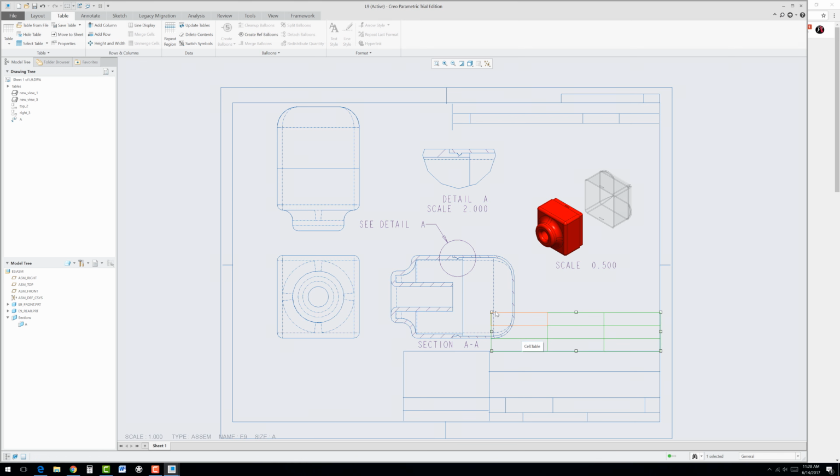To change the size of this, it's really kind of nice. You could click from here, go from left to right, and select that group of cells. And now if you right click, you could go to width and change the width here. Instead of 10 characters, this is only going to have a couple characters, so we could really just go with probably 3. Preview it, hit OK. This one, the same thing. Just click and drag across, right click, width, and we could probably go with maybe 4 on this one. Looks good.